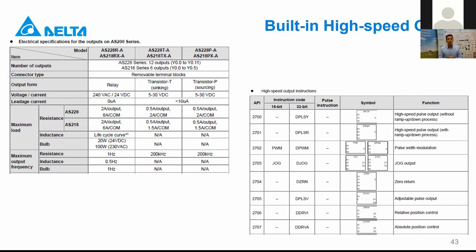Is it possible to install two RS-232 modules on one SCM? As far as I remember, yes, SCM modules support two RS-232 modules. That's fine. But for instance, it doesn't support two CANopen cards. So before using the SCM module, it is good to double check what the possibilities are. But for RS-232, if I am not wrong, yes, it supports up to two.